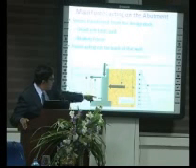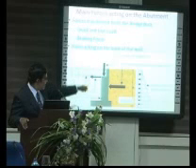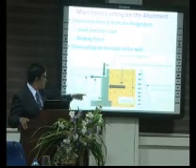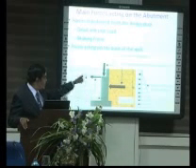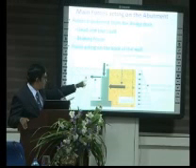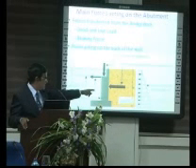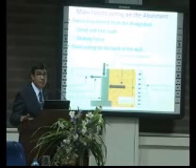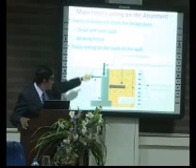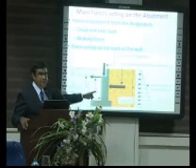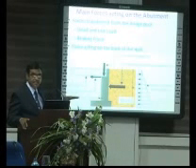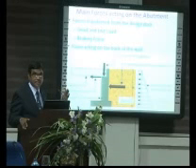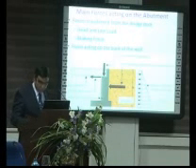Now if you look at that pressure diagram, it has a rectangle component and a triangular component. The rectangle component represents the surcharge pressure, and the triangle is due to the earth pressure. It is a linear variation. You can see the equation there: pressure is equal to Ka gamma times H, where H is the height. So it varies with the height linearly, right? When the height increases, pressure increases. It will be a massive force for tall abutments.